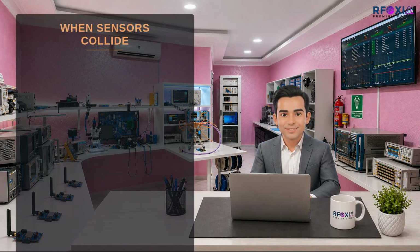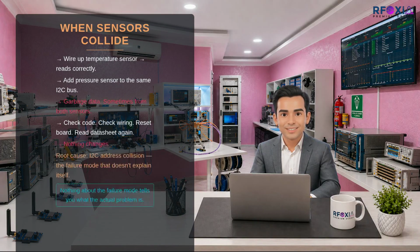You are building a project, you need a temperature sensor, you pick one, you wire it up, it reads correctly, everything is fine. Then you need a pressure sensor, different chip, different function, same I2C bus. Because that is the point of I2C, you share the line, you wire it in. Now one of them is giving you garbage data, sometimes both of them are. You check your code, you check your wiring, you reset the board, you read the datasheet for the third time, nothing changes. What you are looking at is an I2C address collision.